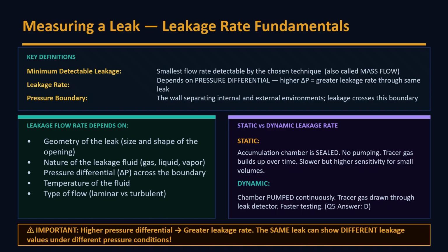This concept appears frequently in examinations. Practical refinery example. Imagine a small pinhole in a heat exchanger tube. At 5 bar differential pressure, leakage may be minimal. At 20 bar differential pressure, leakage could increase dramatically. Same leak, different leakage rate, because pressure differential changed.